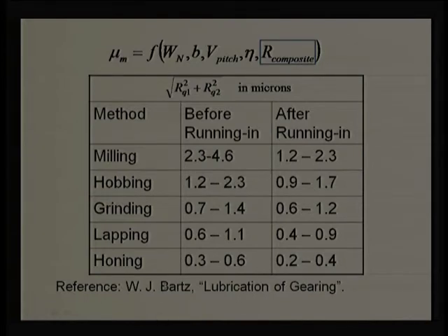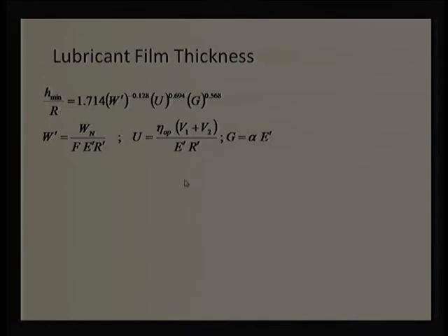And for detail, you can refer to W.J. Bartz's The Lubrication of Gearing, as a complete book on lubrication of gearing. Now, what we talk about, the gear surface roughness, is highly related to the film thickness when we are trying to decide which kind of lubricant regime is going to work in that case.